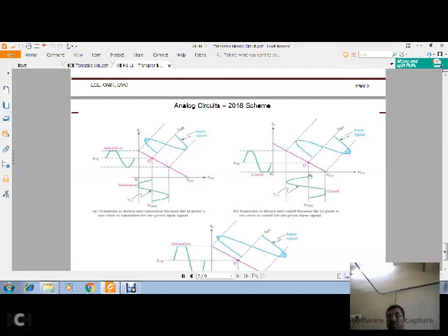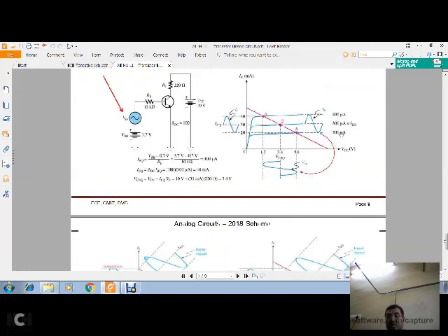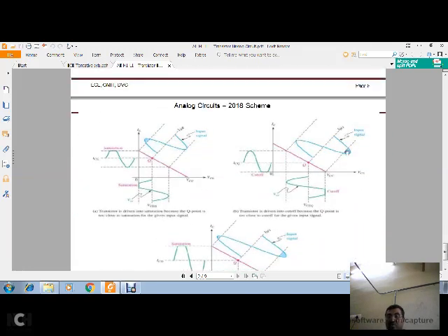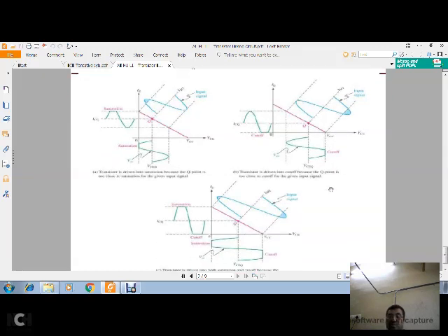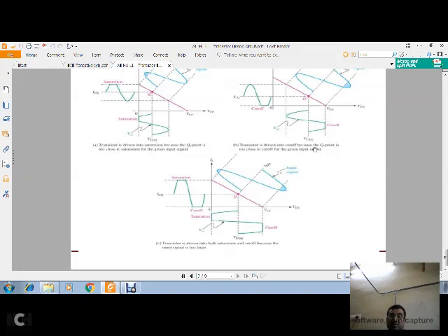On the other hand, if you consider IB equal to 200 microamperes, this is a scenario where you have a Q point just below the middle of the DC load line. It is very close to the cutoff. So if you apply an input voltage something like this, your output voltage is clipped off. Current as well. You can see this is not a faithful amplification.